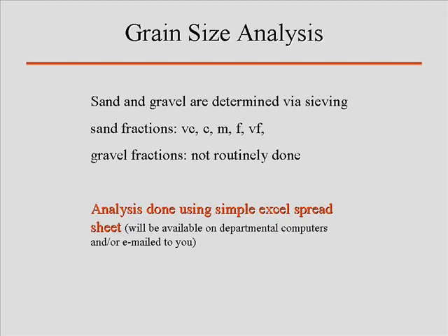Our biggest problem with the hydrometers is they would start bouncing in there. You have to calm it down. And when it starts bouncing, you're suspending things too, and that's an issue. So you have to be very careful how you put it in. There are things called micro hydrometers, but we don't use them very much because they're expensive.